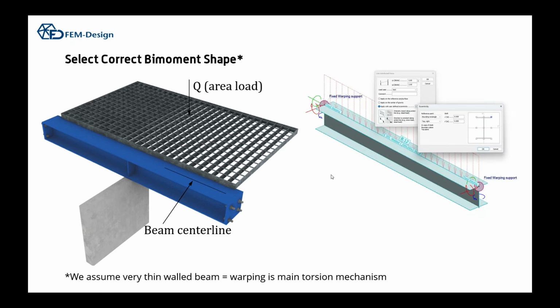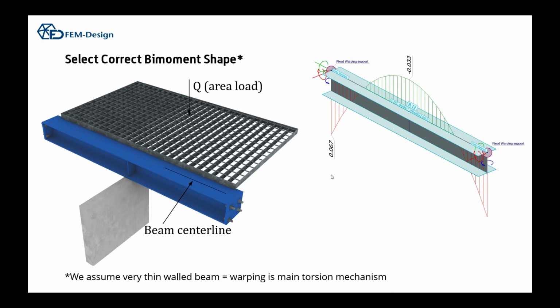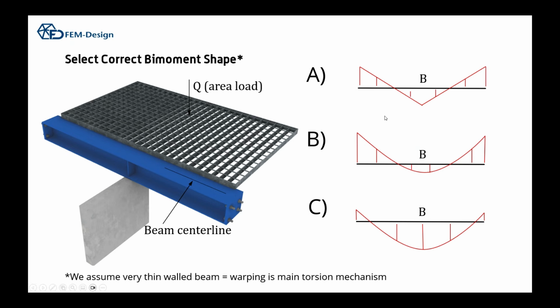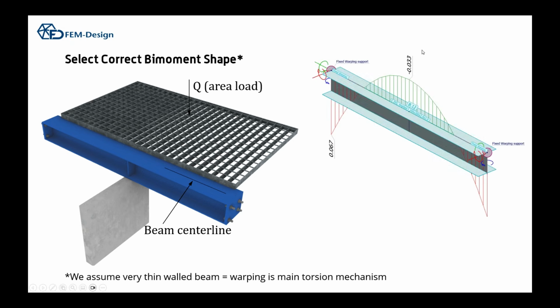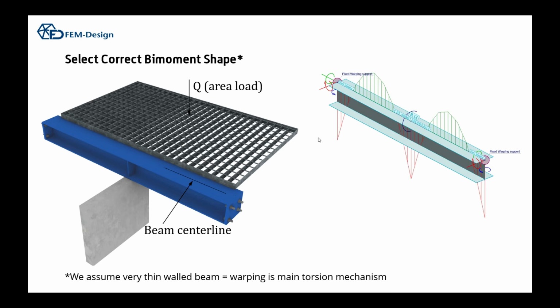Okay, let's do it in our software, and the shape is this one. And if you guessed that it would be B, you would be correct, because the support moment has to be twice the height of the span moment, because it's a bending theory, and you can see the bi-moment is twice the height here at the support, close to the support. But yeah, if you want to inspect those 7-degree of freedom models, it's handy that at least for the I-beams you can calculate something. But in reality, there are ultimately many flanges and bi-moment effects on all of those beam layers and around both axes.